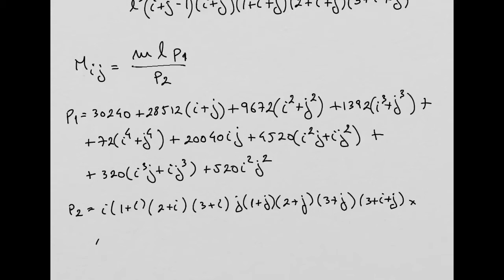Normally, the best way to do this is in MATLAB. You put in the shape functions and second derivatives, and then you ask MATLAB to build the stiffness and mass matrices. It's much easier that way. So this is the hand calculation way, if you want, which is very time consuming. That's why we have computers to help us solve this much quicker.